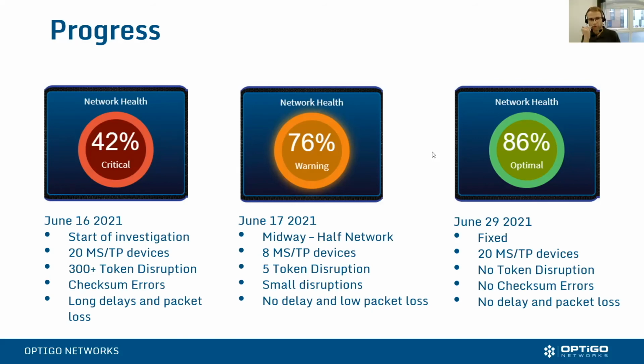I've actually deployed them using PoE, Power over Ethernet. I've found an adapter to power them that way. So again, I haven't had to install separate power supplies for them either. That's fantastic. That helps a lot. And they are DIN rail mounts, so it's very, very quick. You don't have to worry about sticking it anywhere. If you've got a panel already that's sitting on DIN rail, it's a simple click and away you go.